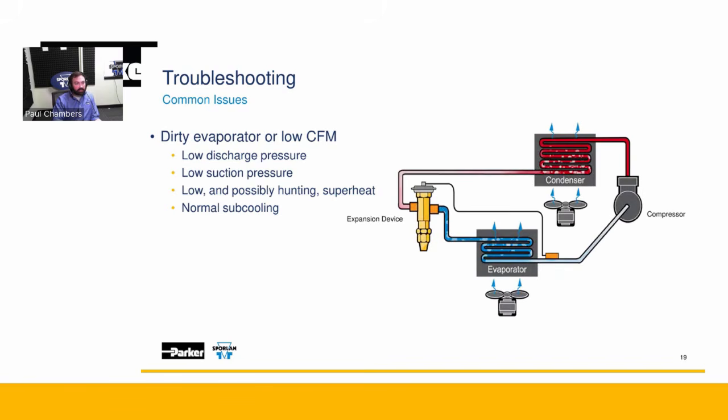Another issue we're going to see a lot is going to be a dirty or low CFM, cubic feet per minute, airflow evaporator. This is where you see the evaporator doing the work. Usually that's an air to refrigerant heat exchanger. It's really easy to just not clean those, right? I was talking with somebody, a friend from church, and he was saying that he had never changed the air filter in his house. Didn't know that was a thing that he had to do. He had lived there for a couple of years and never changed it.